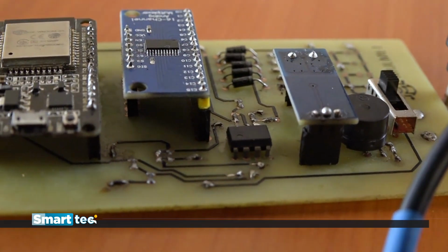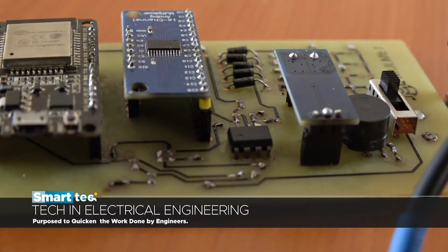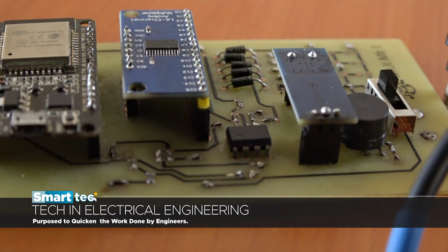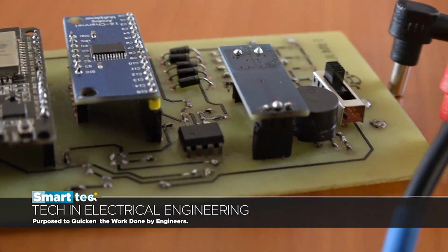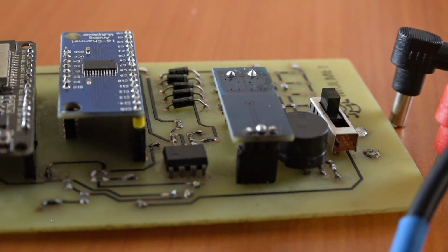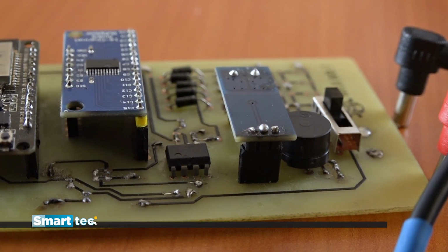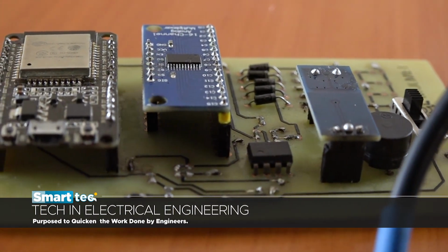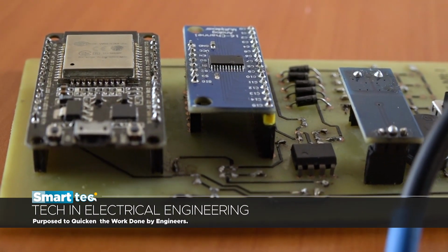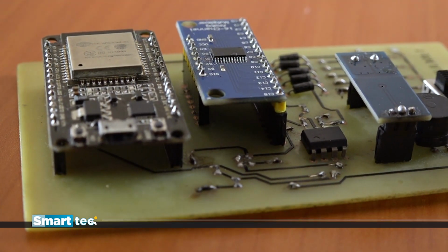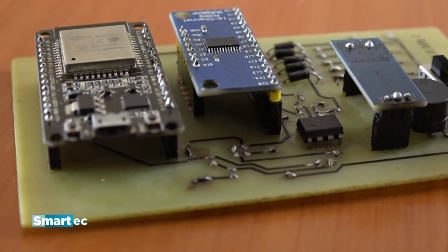Inside it is divided into two sections. The analog front end, which is this section. So this section is basically supposed to get a signal, let's say, from your voltage lines, let's say your socket, which is a very high signal. And this signal is supposed to be put into levels that are easily read by this small one. So it basically converts a big signal, whatever signal it is you're using, to a suitable signal for our device.